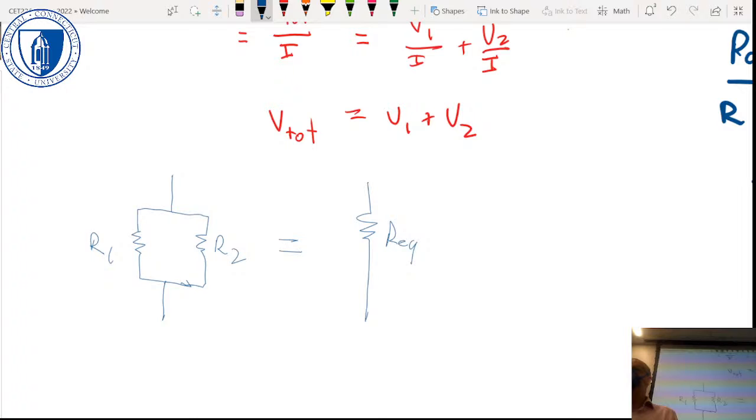Right, so V in equals I in times R1 plus R2, because R1 and R2 are in series. No other current flowing, we haven't connected anything up to these terminals. So we've just got I in. So V out is just I in times R2.